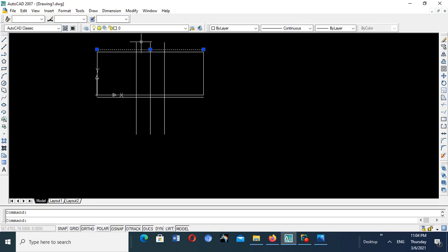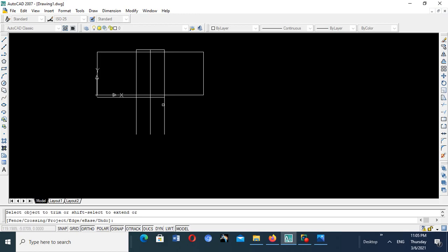Now I can click anything, it will be trimmed. Check this. That is good. Oh no. Let me start again. The command TR and enter. Then they say now start clicking and see that is gone. That is taken up because of that short command. You could use the other command that I taught you yesterday, but this one is a shortcut command. You must know these shortcut commands.